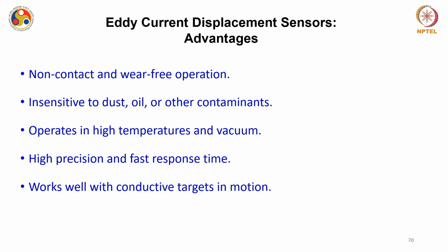So there are various advantages associated with these eddy current displacement sensors. The first and foremost advantage is they are non-contact devices, and therefore have wear-free operation. They are insensitive to dust, oil or other contaminants.